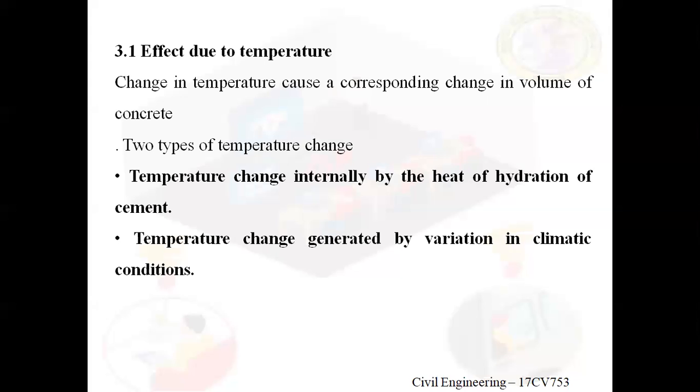There will be a difference in temperature from one place to another in the same element. Thereby there will be temperature changes which cause some changes inside the element. That means where the heat of hydration is more, the internal cracks will develop. Coming to the second one, temperature change generated by variation in climatic conditions: we know that in the atmosphere, there will be changes in the temperature.